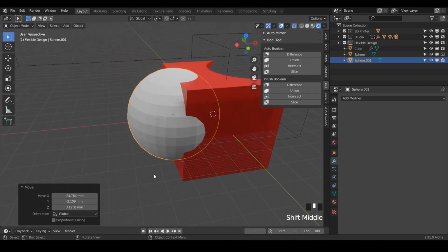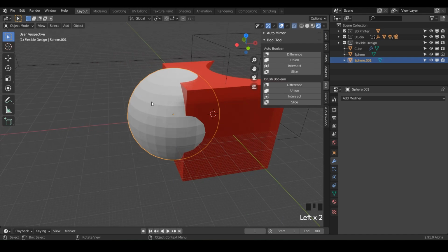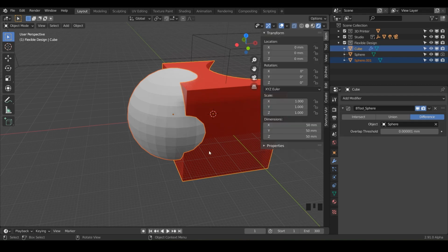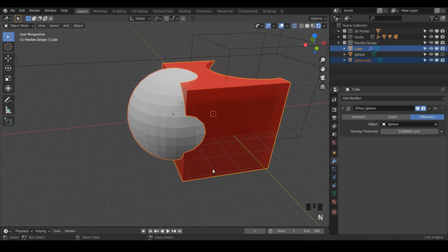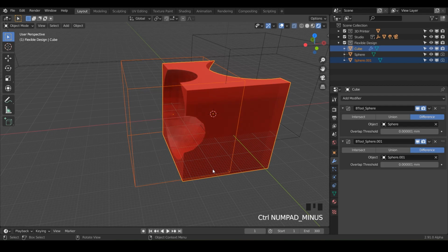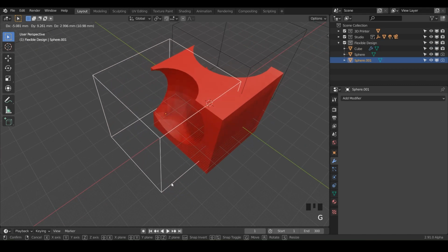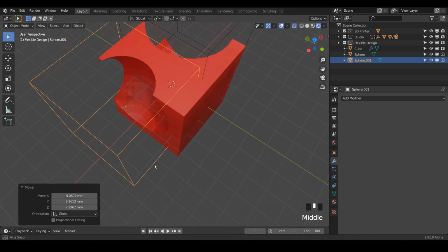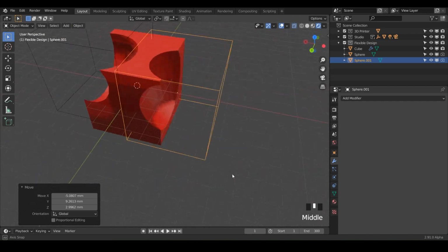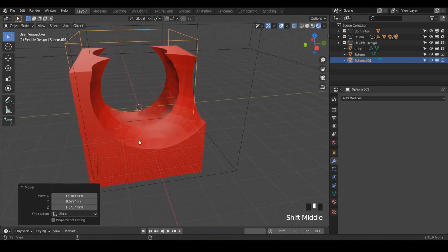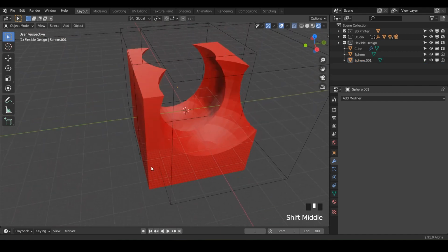And a quick way to do the same thing we just did is click on the object. I want to subtract this object from, while holding Shift, this object. And instead of hitting the button here, what I like to do is just hold Control and minus over on the far right side of your keyboard. So Control minus, looky there, and that has activated the brush Boolean difference. So get in the habit of using that keyboard shortcut, because then you can Boolean like a banshee and just be BoolTooling all over the place. So, you know, it's a very fun way to do Booleans. And look at that, I made a very crazy, I don't even know what that is, but it's very cool.